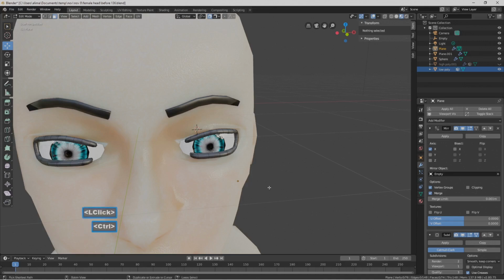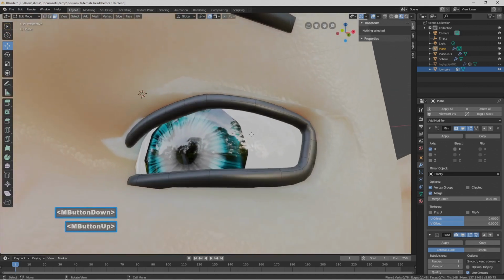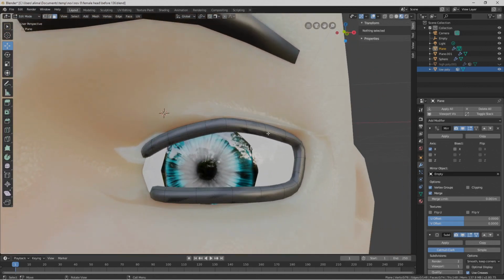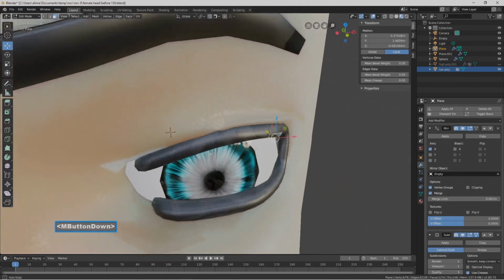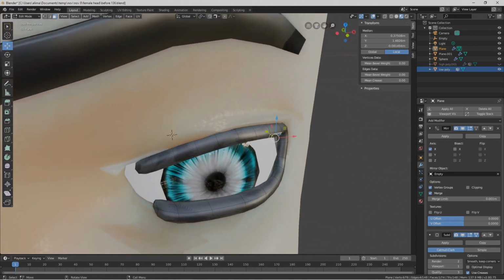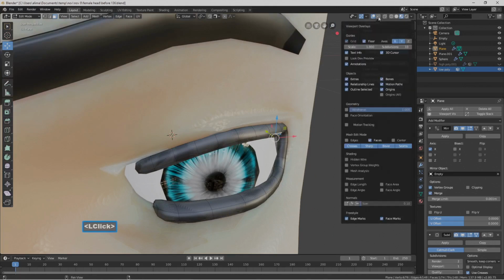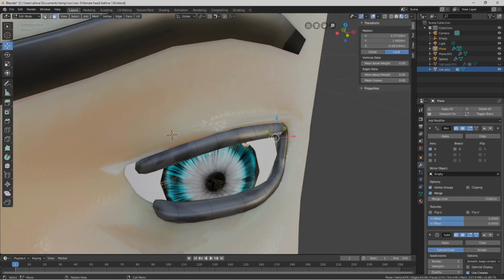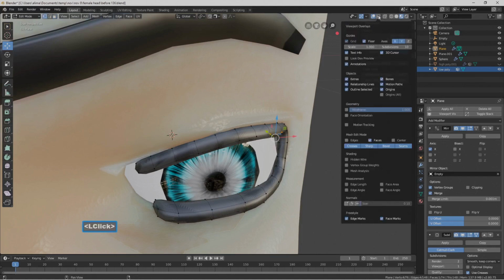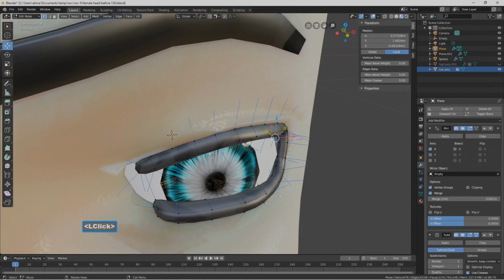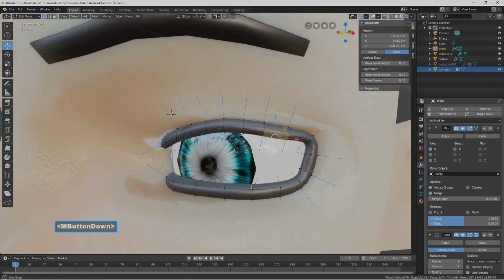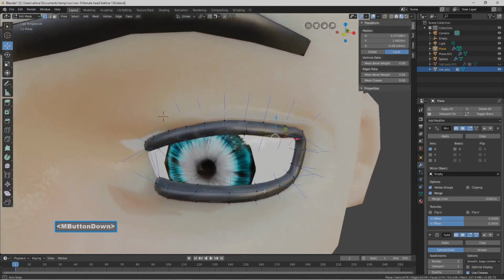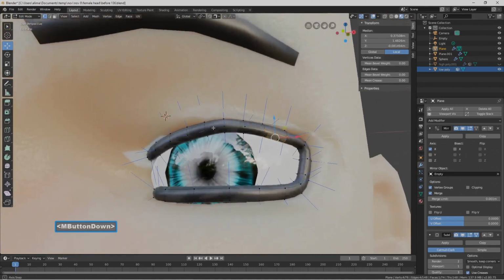Let's go to edit mode. We're going to turn off our snapping. We have a strange looking color here. So what I'm thinking is the normals are probably not right. We can check the normals by, let's go to vertex select. Okay, so to the upper right, we come down and your normals look right. Normals are coming out like they're supposed to.